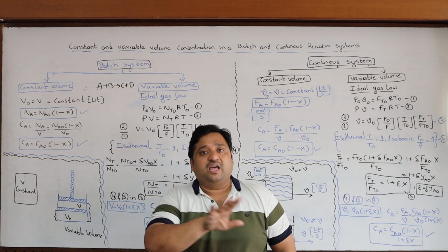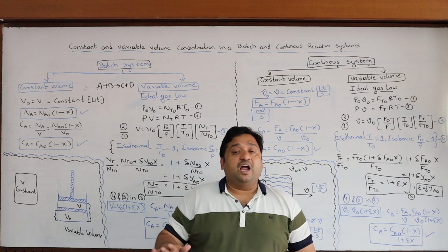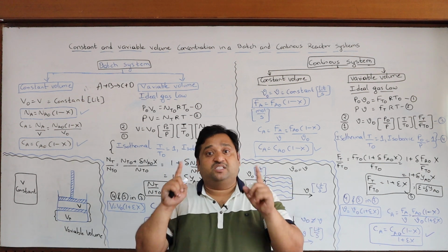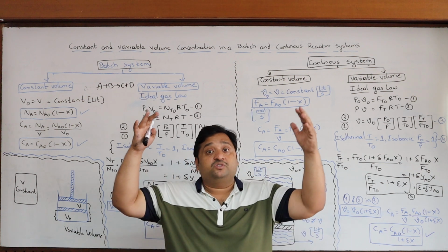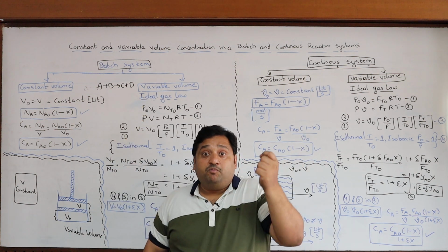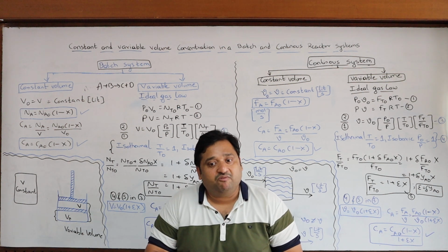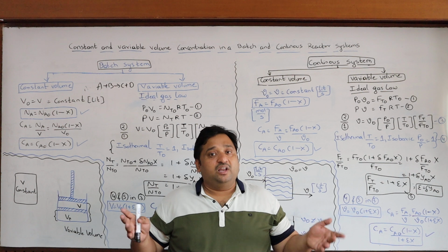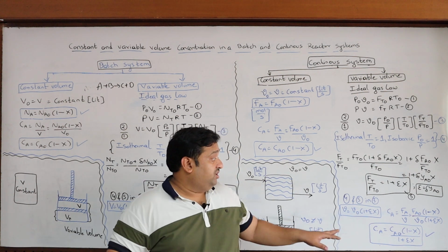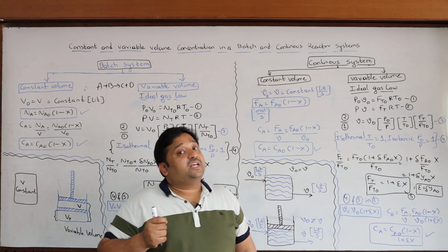If the same reaction happens in liquid phase systems, the liquid volume will not change, because liquid is incompressible. Whereas if the same reaction happens in the gas phase, volume expansions and contractions happen, because the volume of a gas is easily affected by the change in moles. As long as it is a liquid phase reaction, you don't see any volume changes. Whatever we are discussing is very important for gas phase reactions.